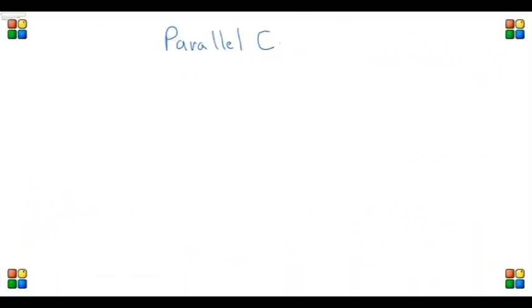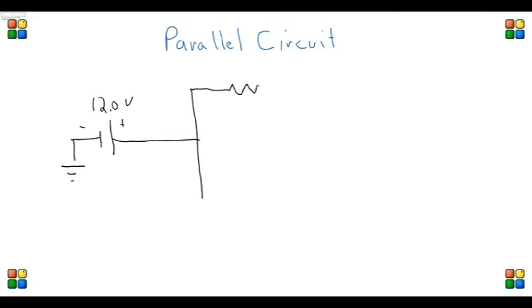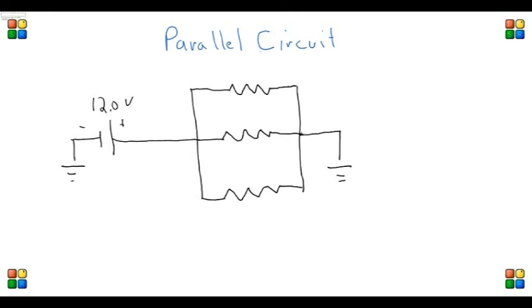Flip over to parallel circuits. It's really not that much different if you visualize the charges. So we'll draw one of our stock parallel circuits in schematic form and put 3 resistors in it. So that's 3 paths that those charges can travel in. And we'll give a value of 8 ohms for the top one, 8 ohms for the middle one, and 4 ohms, which is a little wider, for the bottom.